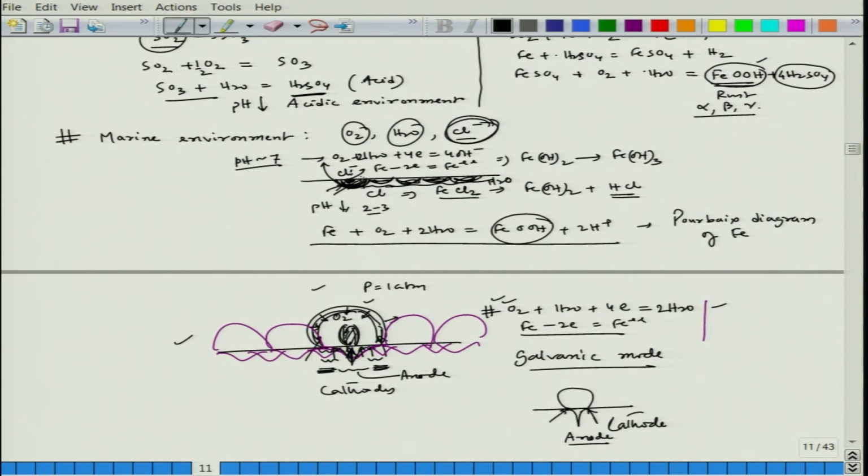Before I end, I would like to show you uniform corrosion what we experience. For example, this is a dog bone like tensile sample. Okay. So, this tensile sample, if you see the top part, this was polished, this was actually machined and then I have kept it in my home, inside the house, and this is lying there for almost 3 months. And if you see the top part and the center part also, it has started corroding, and the corrosion is more or less everywhere, and this is a typical example of uniform corrosion.